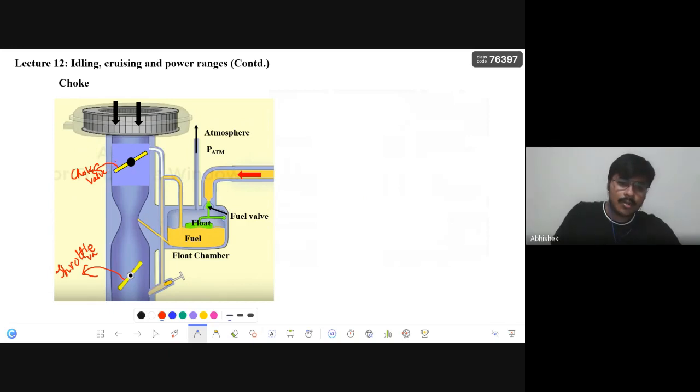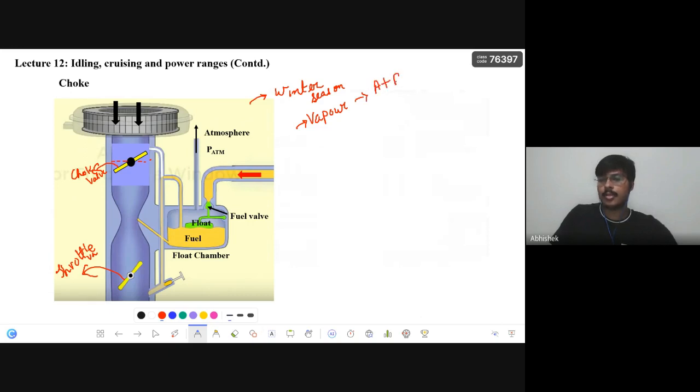But the main reason is that when we press that switch, this choke valve will close or slightly open. Generally, we do it in winter. In winter season, the engine is already very cool, so the fuel is not getting enough heat to get vaporized and form an air-fuel mixture to get combusted. This is not happening. That is why we have to supply more fuel.